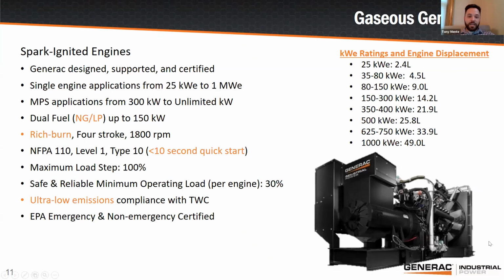So it's a very short time that you'd even see any sort of outage. And if that's an issue, we can put batteries with it so that you would see no blip in anything. In a hybrid offering like that, the batteries would cover the gap for the 10 seconds and then the generator would take over.